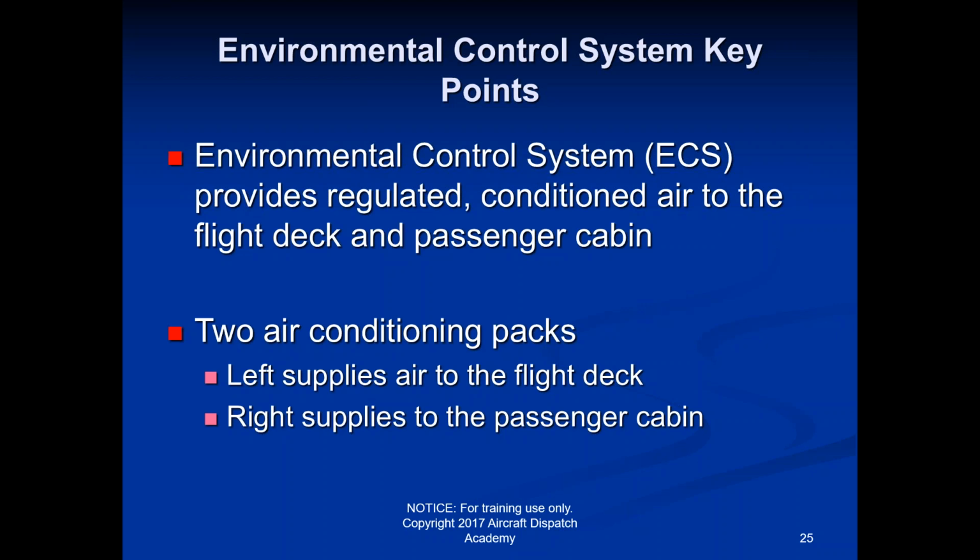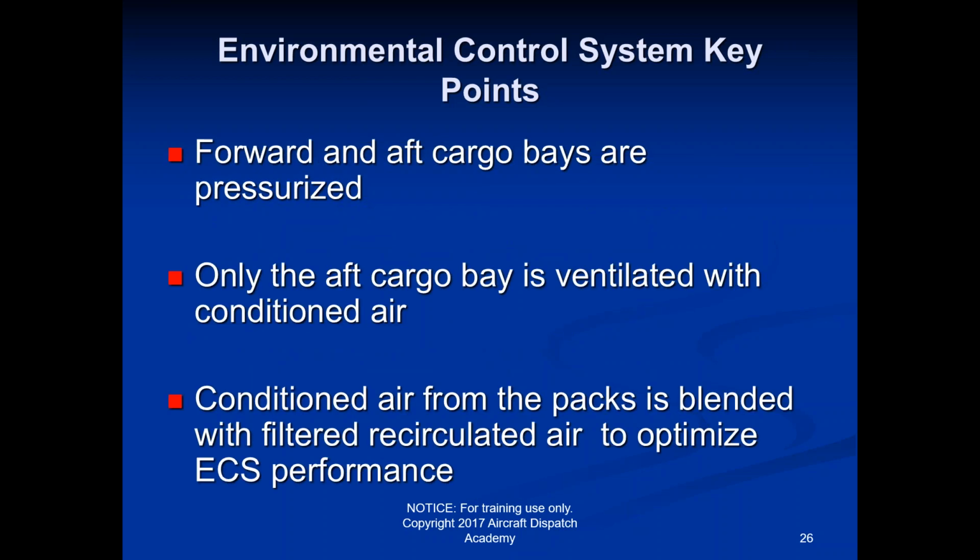Of course, like I said, either of these two packs will do the work for the other one. So even if the right one is out, the left one can still provide air. Obviously, it still has to provide air to the flight deck, right? And vice versa. If the left one is out and they're relying on the right one, the best air that it's going to provide is to where it normally is supposed to. If it's having to take over the duties for the left pack, it will send the air that way and the air will reach there, but it's just not as powerful. If you flip-flopped it, and the left one was working without the right one, the flight deck would still feel normal and the passengers would still get air, but it would feel less than if the left one was out. So anyway, it's kind of a funny thing to watch for.